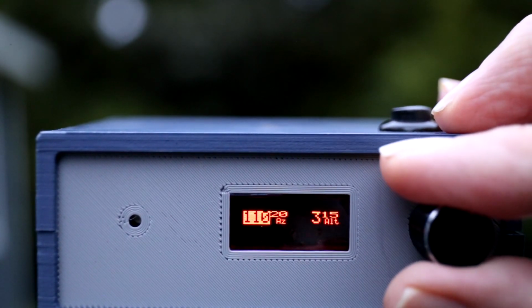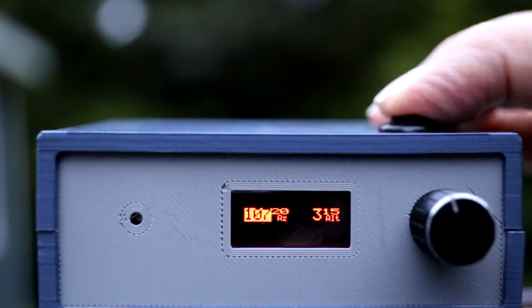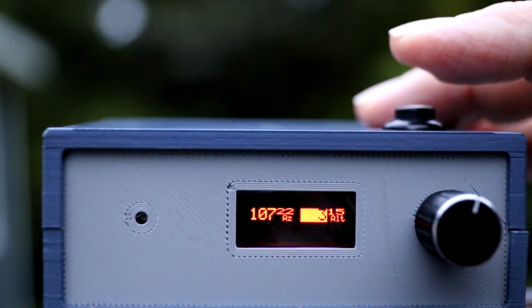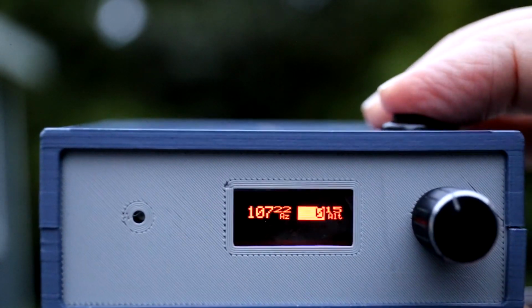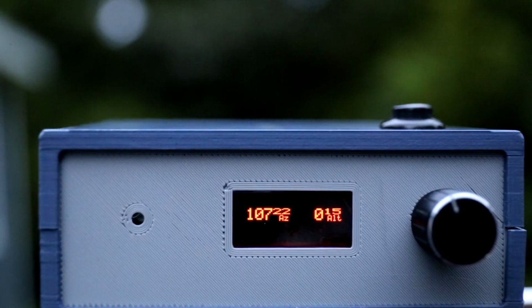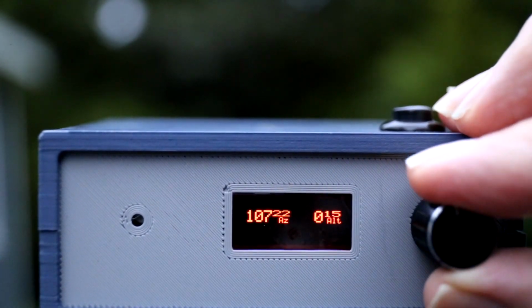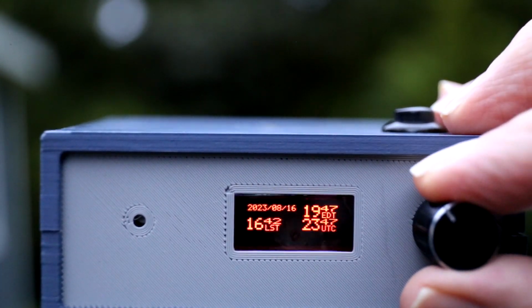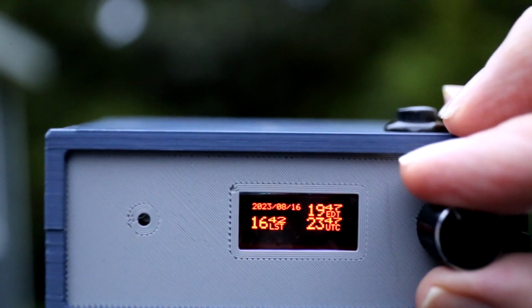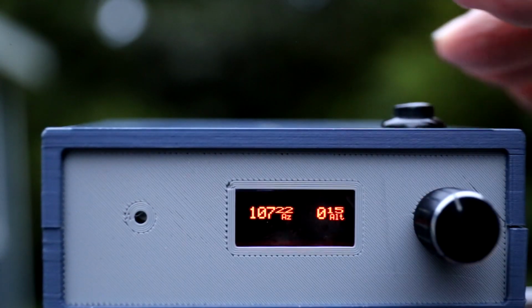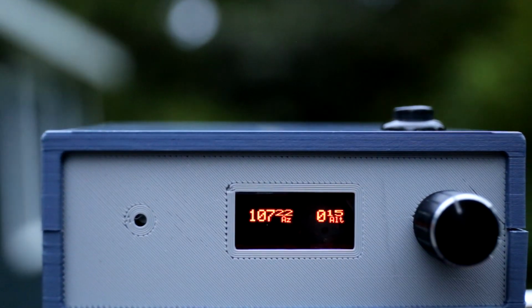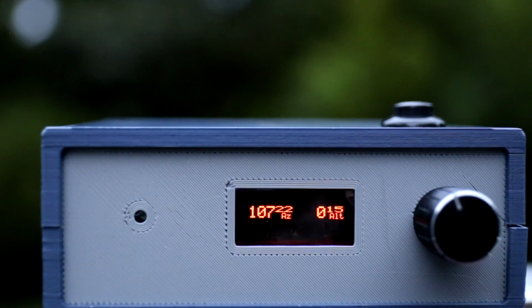Each following single push on the button advances focus to the next adjustable value. Each focused item can be adjusted by the encoder. After the last value, focus is said to be on the page, where the encoder can select the next page or the previous page. Again, while in manual mode, the sensors don't contribute to displayed values. So changing the line of sight has no effect on displayed values. Even the real-time clock is in effect disconnected.